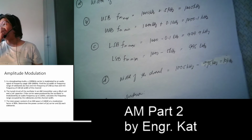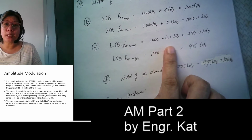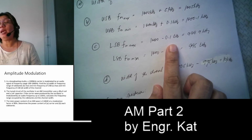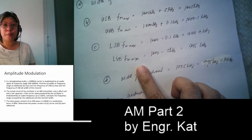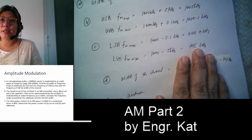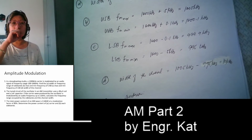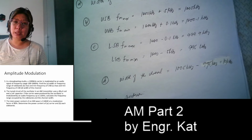For the lower sideband maximum, we have 1000 minus 0.1, which gives 999.9 kilohertz. For the minimum, we have 1000 minus 5 kilohertz, which gives 995 kilohertz. Again, why two values? Because of the minimum modulating signal and the maximum modulating signal.